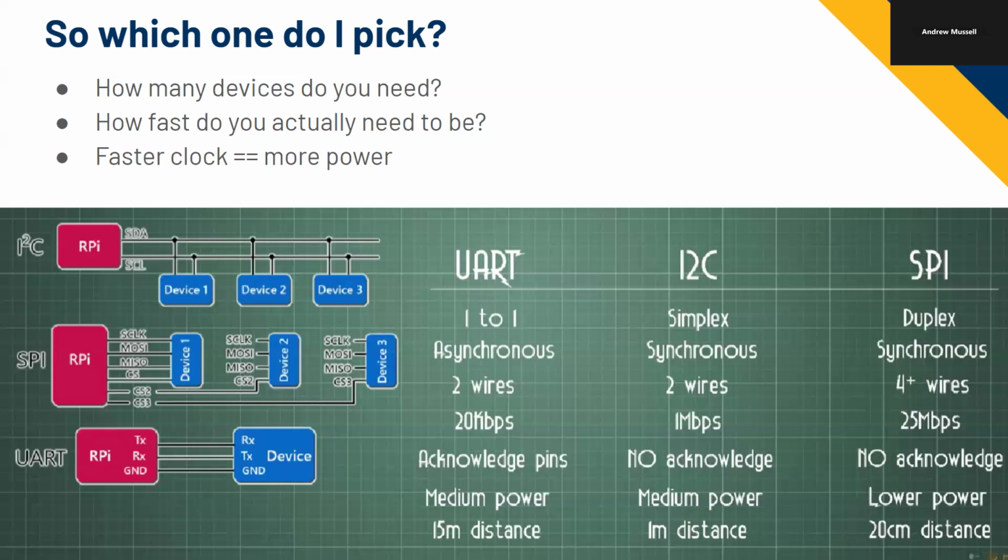And I2C is also simpler. So if I want something that might be slightly more robust, might not break as much, that's not to say SPI isn't reliable. SPI is also very reliable, but if it's simpler, then there are fewer things that could go wrong. If I don't need all the bells and whistles that SPI provides me, I2C might work better.